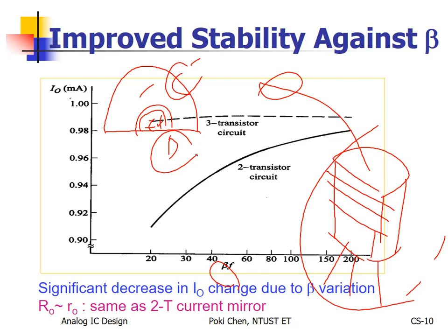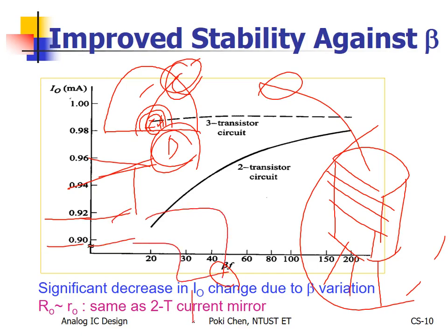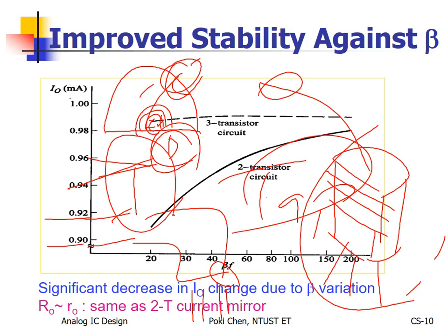And then the base behaves as a controller, just like the tap, right? To turn on the water, to turn off the water, and how much water you would like to turn on. So the base is a controller to control how much carriers emitted from E will be collected by C. That's it. As a controller, just like the tap, the water here, right? 水龙头. So according to such a switch, to turn it on, to turn it off, what would you expect to have? This is the emitter to emit a lot of carriers, then the collector here to collect them, right? And a base here to control. Sure, you expect all the water will flow from E to C instead of from B. Otherwise, you have some kind of water leakage here.